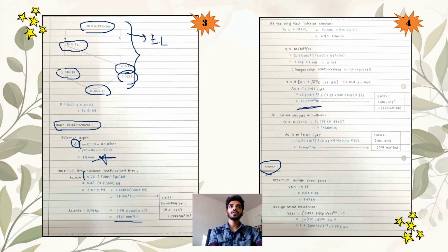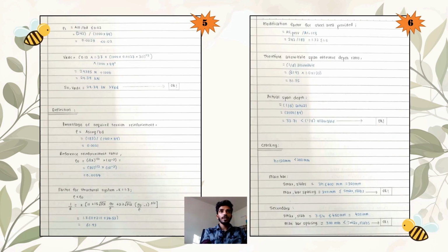So we are able to see what the next step is about. Here we have identified the V_Rd,c. After all the calculation, we are able to get 29.39 kN, which is more than V_Ed. So the statement that we conclude from this is that it is okay.